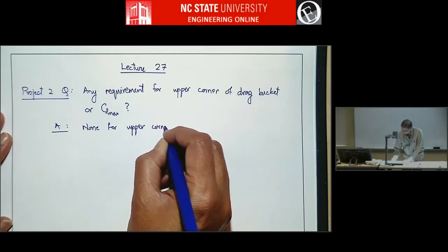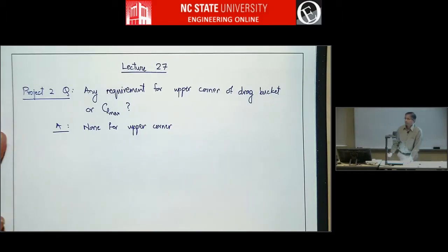Okay. The reason I asked that is because when it asks us to specify the transition, the 50% in part A, it says for the low drag region, so that would just be between the lower end of the drag bucket and whatever the upper end happens to be. Yes. So somewhere near the middle of the drag bucket, both upper and lower surface will have laminar flow at least until the end of the favorable gradient, which is what you're going to set, as required in the question.